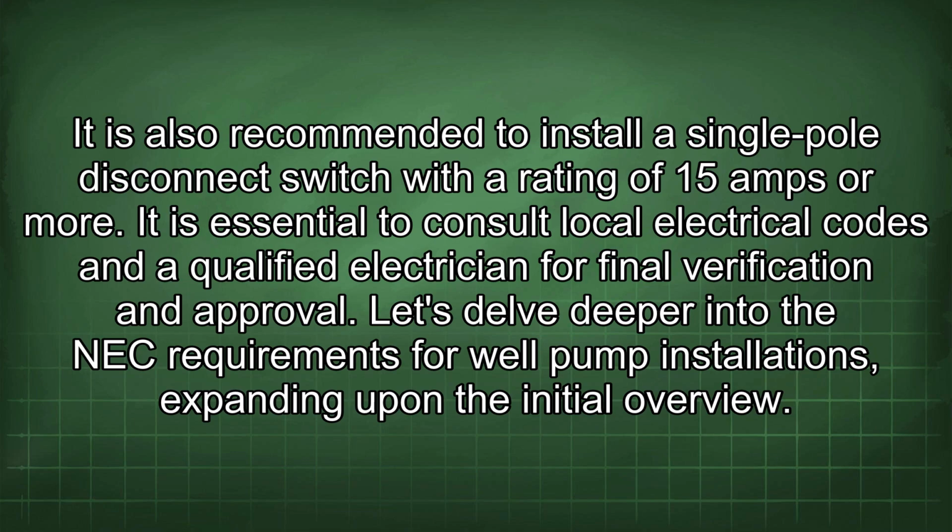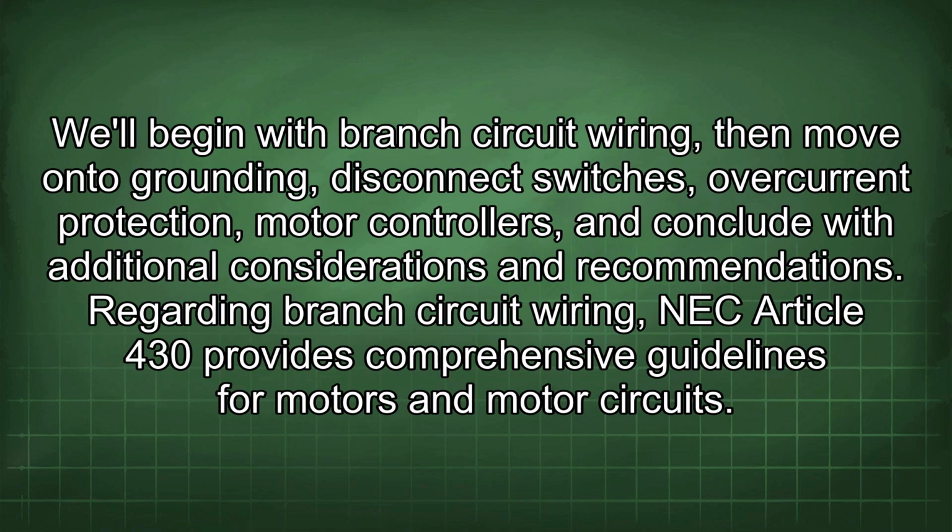It is essential to consult local electrical codes and a qualified electrician for final verification and approval. Let's delve deeper into the NEC requirements for well pump installations, expanding upon the initial overview. We'll begin with branch circuit wiring, then move on to grounding, disconnect switches, overcurrent protection, motor controllers, and conclude with additional considerations and recommendations. Regarding branch circuit wiring, NEC Article 430 provides comprehensive guidelines for motors and motor circuits.